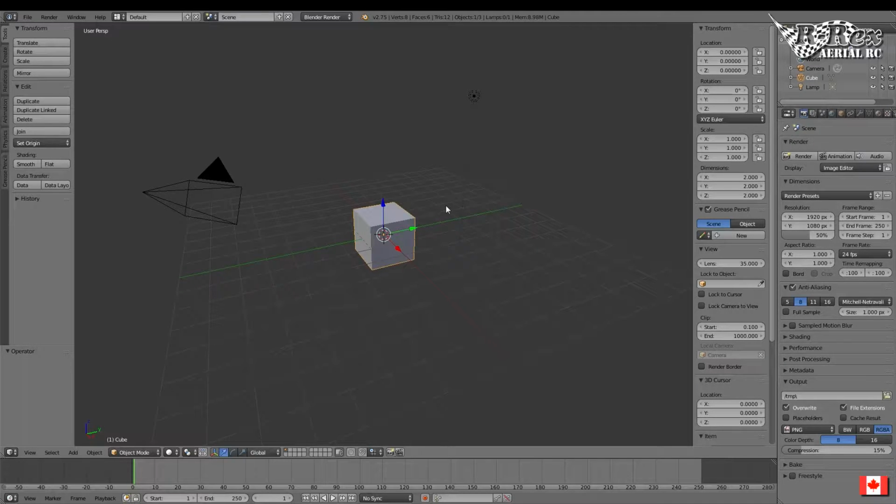For this tutorial, I'm actually going to make a micro drone frame. So I'm going to show you how I built the one I have. The great thing about Blender is you can create an object and then use another object to cut out other objects. So for example, this is a micro drone, so it's going to have 4 motors that are 8.5 millimeters wide in diameter and 20 millimeters tall. So instead of trying to create a cylinder to encase that, I'm going to actually create the model of the motor to use for that.